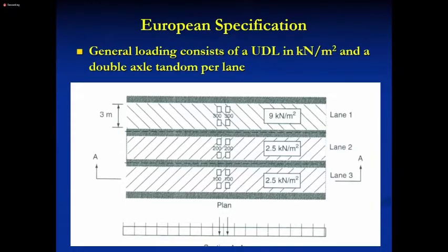So see whether you can generate the bending moment envelope using Midas automatically. I think it's possible to automate it. Once you ask it to try all the load cases and find the bending moment envelope, it will find it for you. I have not used it, but others said that it can be done. This is one of the features of Midas. You don't have to do it manually. You can ask the program to generate the bending moment envelope. See how to do that, right?